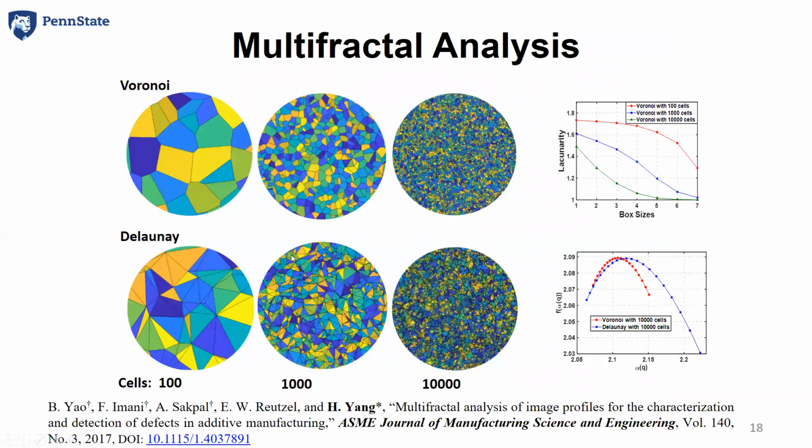As we can see, we can do the defect characterization at different scales. This is a large scale, and we can get into much finer scales like this, and then even go further. If the distribution of particles or the quality in each area is different, we're characterizing the defects in each grid. There will be different behaviors if the distribution of the build quality is different.